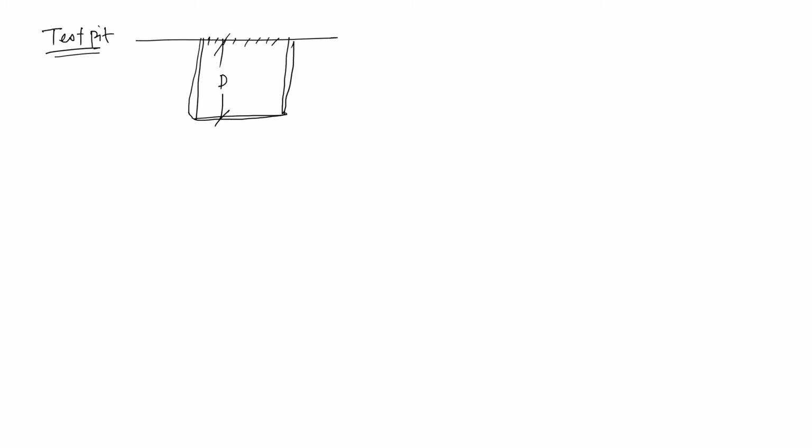Now we talk about the test pit. It's a simple thing, this is your ground and here you should excavate and make a dig. After digging, this is your excavation pit. The specification of this test pit is that the width is 5 times the test plate.